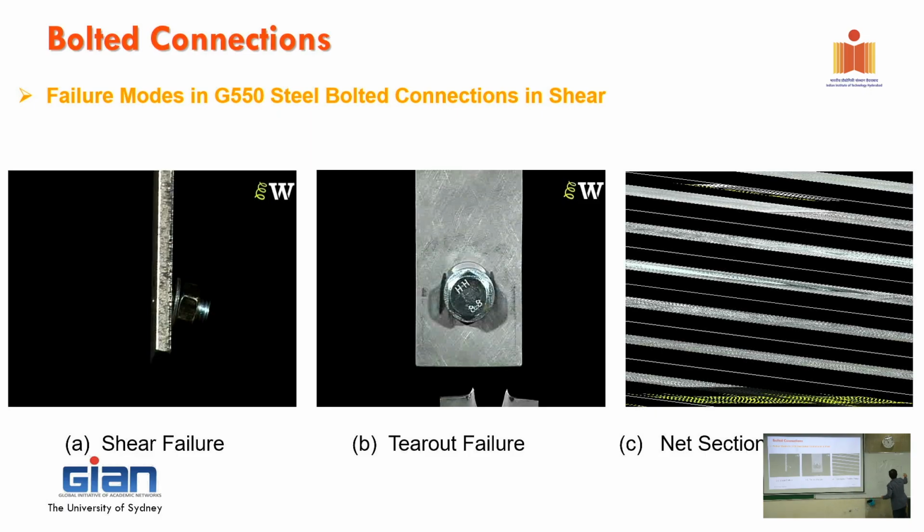And with bearing, if you have a bolt in here, it just keeps going in like this one. So this is bearing, okay? Usually the tearing may happen since it is at the edge, it is punching out. Otherwise it should be perpendicular to the application of forces. So this is the direction of flow. Fracture will happen perpendicular to the... Oh, that is the other, yes. Since it is at the end, you are having such a... So that is the other failure mode.